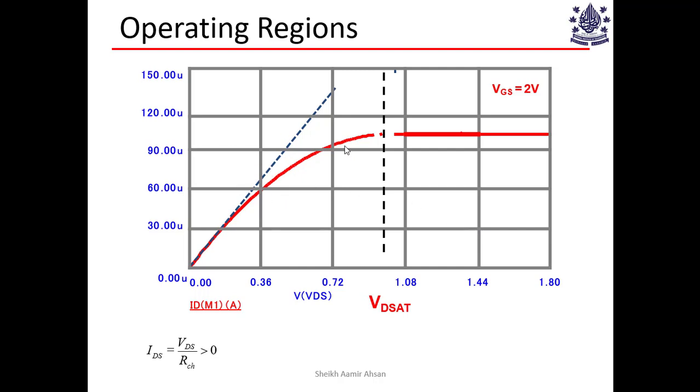Now this over here is called the linear region, but note that it behaves linearly only in a very small range of voltage, close to 0. As you go on increasing the voltage, the linearity is reduced. You go to a nonlinear behavior. This over here is called saturation, because the current saturates now, it remains flat, and this is called the linear region or the triode region. And this voltage where this saturation happens is called the saturation voltage, right? And it is given by this equation.